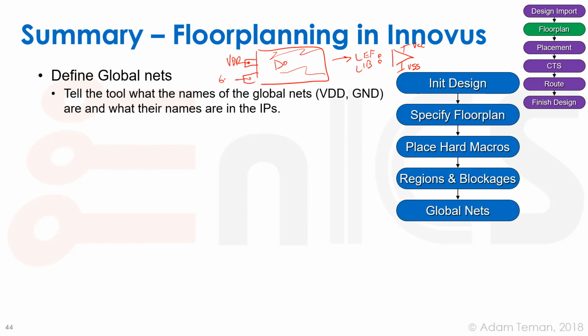but we called our pin here ground. So how do we get VDD to connect to VCC? Well, that's what we do with what we call global nets. We say there's a global net called VDD, and all the inverters should connect the VDD to their pin that's called VCC. Remember, when we have multiple power domains, we're going to have something like VDD1 and VDD2, right? And so therefore we're going to say an inverter in here, its VCC should connect to VDD2, while this should connect to VDD1. Anyway, that can also get complex, and in our UPF, CPF, we can define those things.